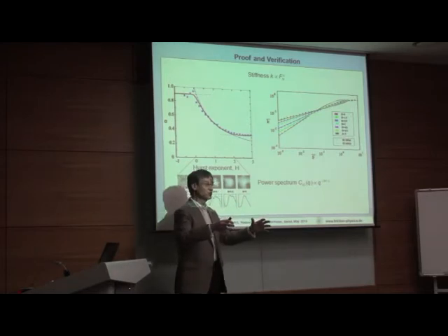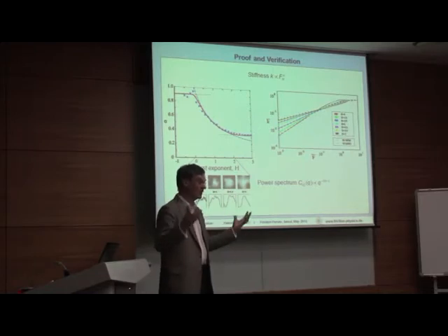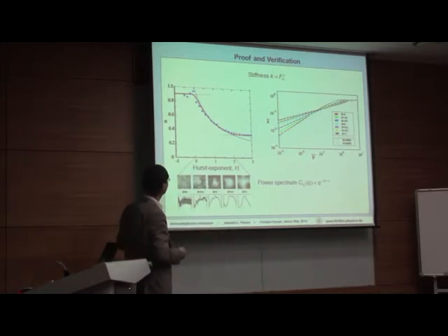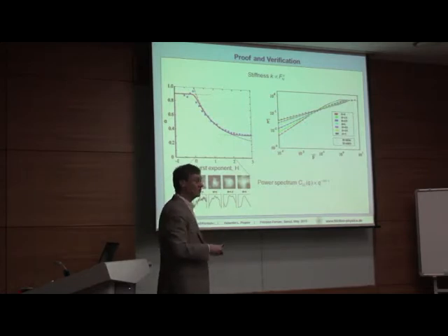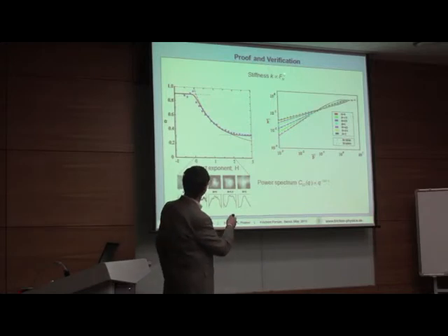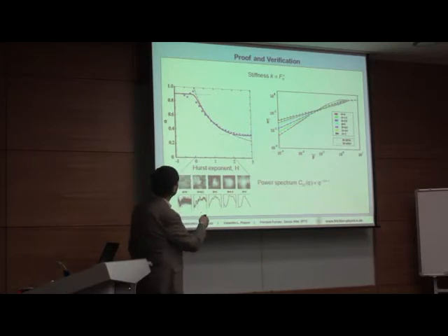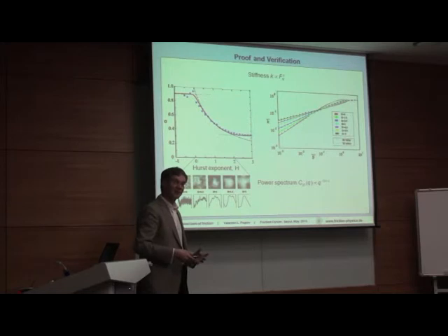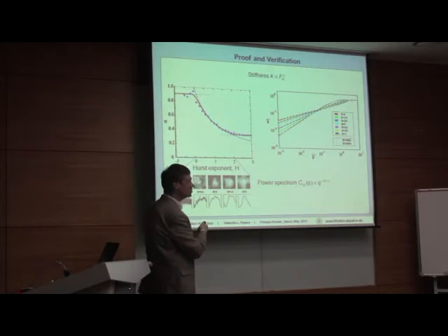And these are smooth Hertzian ones. So all spectra of surfaces which one can imagine are included here. And we found that for all these surfaces the stiffness is a power function of force at small forces, with some power alpha, and this is alpha as a function of the Hurst exponent. This is some region where they are really self-affine, and there is even a theoretical, analytical prediction for this part.